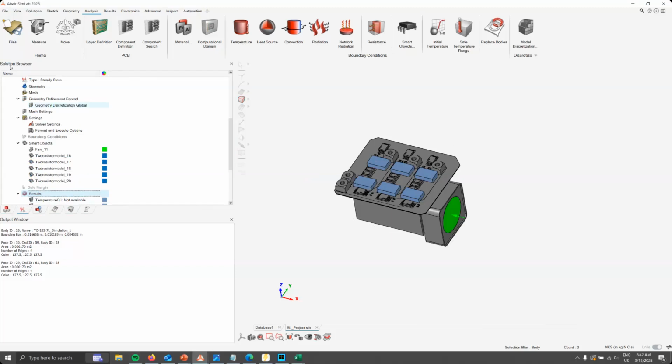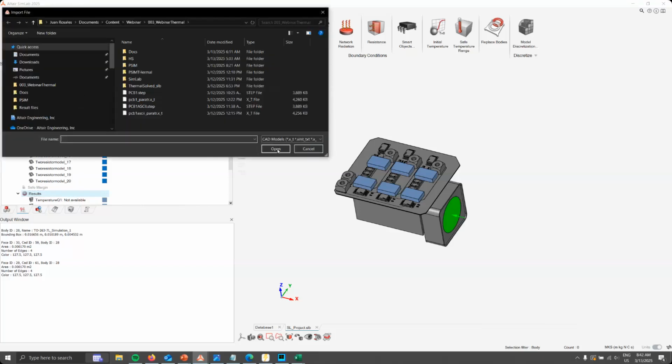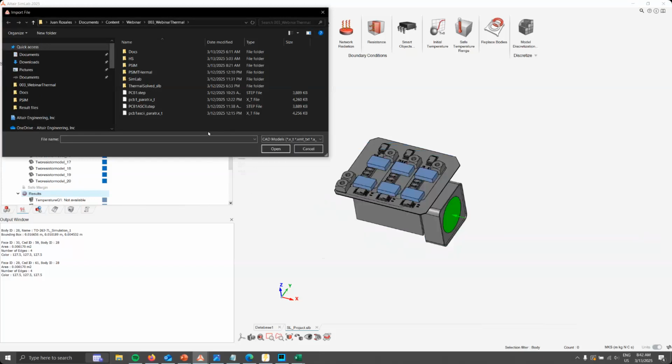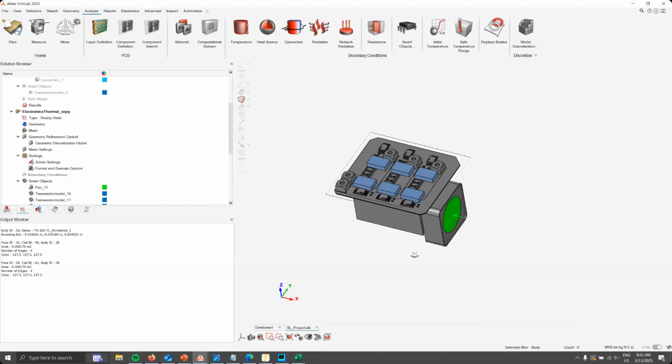Yeah, correct. So as we can see here, and let's skip the solving part, if we go onto import and then CAD, some of the file formats that we're going to find is Altium, or we have this ECAD section. In this ECAD section, we can import an ODB++ or an Altium Designer or an IPC 2581, Siemens, Cadence Allegro. All of those files are here. And if those file formats include the 3D models of the components, this will be included also inside the simulation.